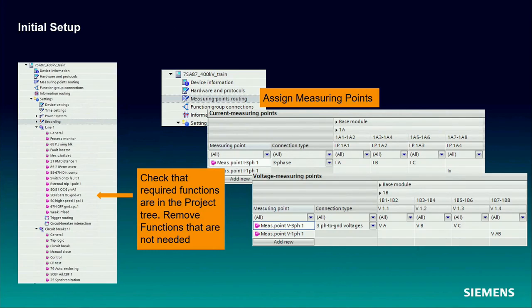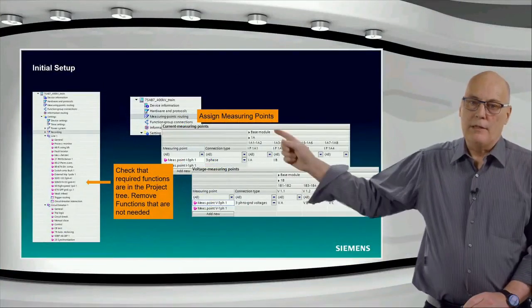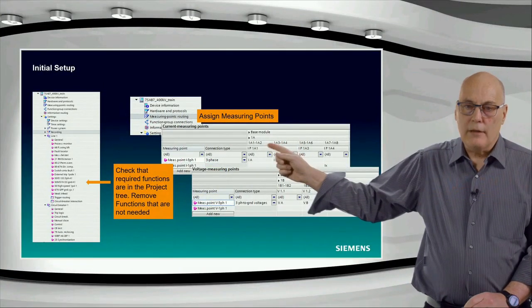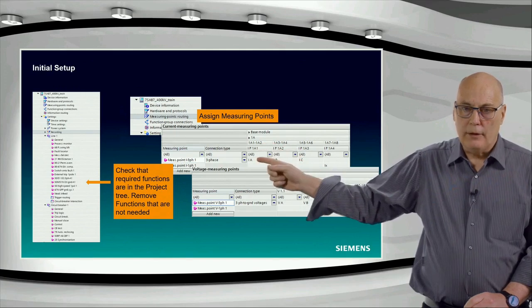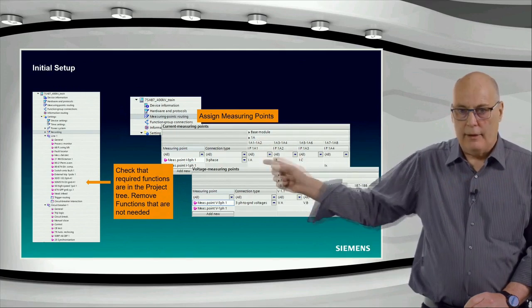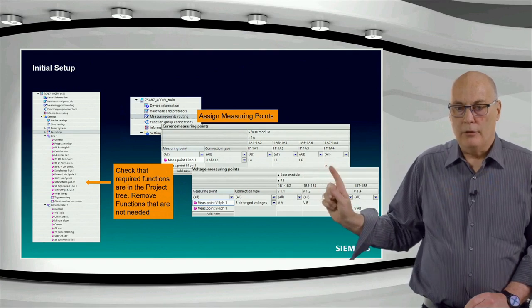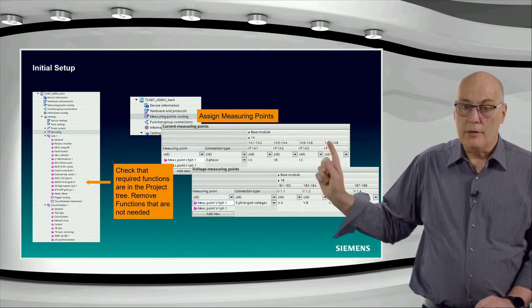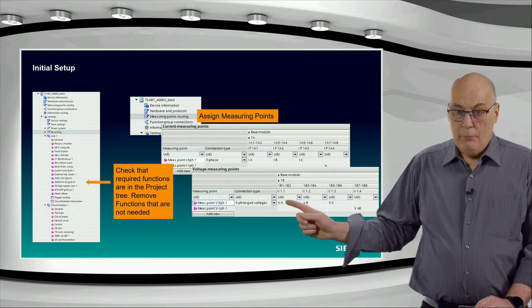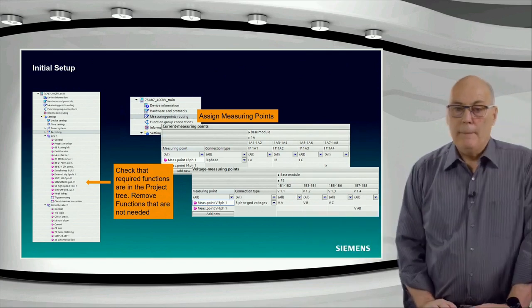Also important, if you have to work with a relay on site, you don't need to refer to any manuals or pamphlets to find the terminal numbers. In DIGSI, you can see the terminal number of the device at the top here. There is the actual physical terminal, and the IA phase current is connected there, and so on. And the parallel line residual current, as we'll see later on, is connected to this terminal here. At the bottom, the voltage in a similar manner.